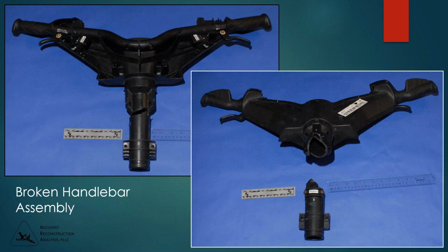Next example is a broken handlebar assembly. So this is an injection molded plastic component, has various types of reinforcement that fractured in service. And again, we were not permitted to perform any destructive analyses on this. But again, you can see the steering column at the bottom, we've separated the two in the right image to show where the fracture occurred between these components.